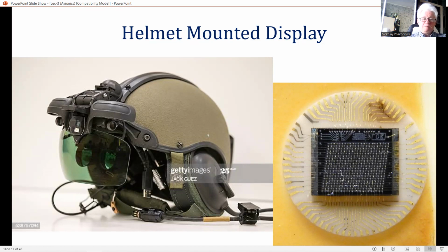The problems become more acute at night, when the eye without the display sees very little, and the effects have been experienced when night flying with a monocular system in a helicopter. It has been shown that a binocular system, whereby the display is presented to both eyes, is the only really satisfactory solution. And hence, current HMD designs are generally binocular systems.